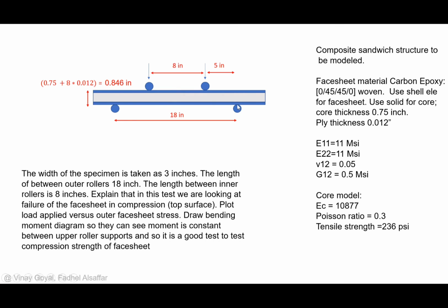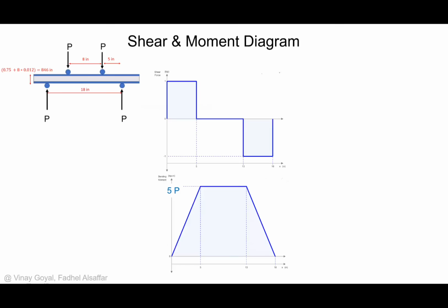We substituted this forward by simple support, and we had a small area here, and we applied pressure on top of that, and we solved element for the core, shell element for the lamina, and that's what we did. We went through the assembly step, creating the outputs, and then interaction, applying load, boundary conditions, mesh, and then running the model.